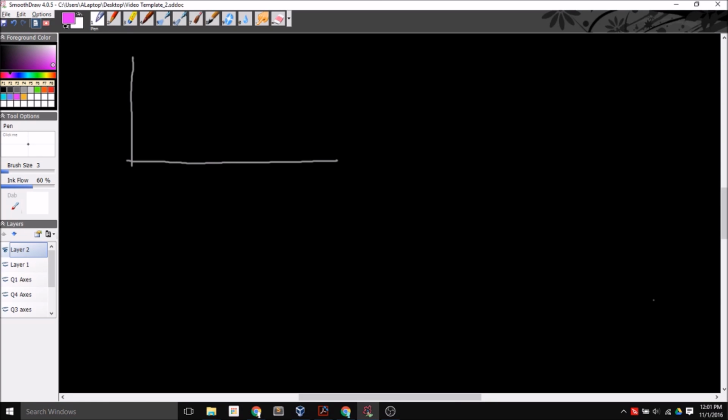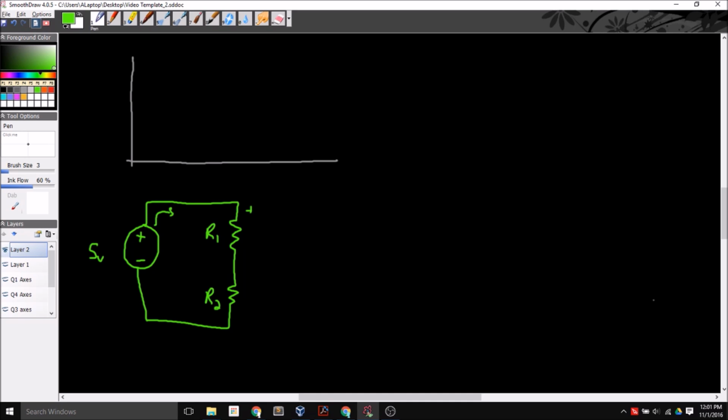What does the circuit actually look like? Well, if you would recall, we had discussed a circuit in which we have a power source and some series resistors. And we were able to calculate, given the values of these resistors, the voltage across each resistor. We were able to do that by converting this into a single resistance, then using Ohm's law to find the current, and then breaking it back apart, and using Ohm's law again to find our voltage across any particular resistor. There's actually another and an easier method of doing this, and it's called the voltage divider rule.